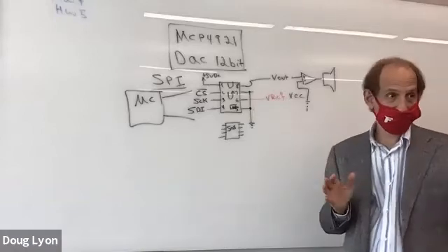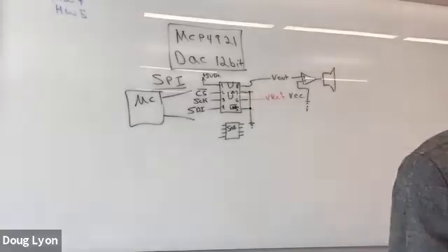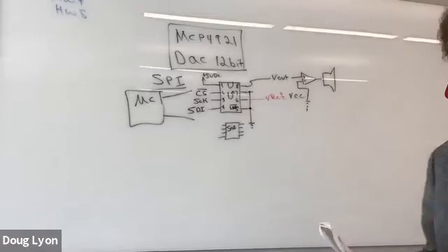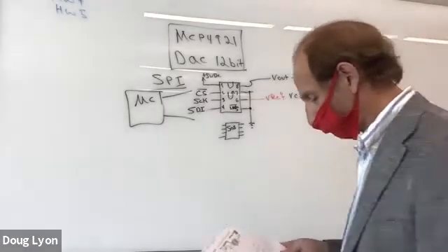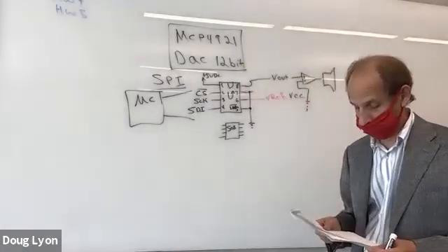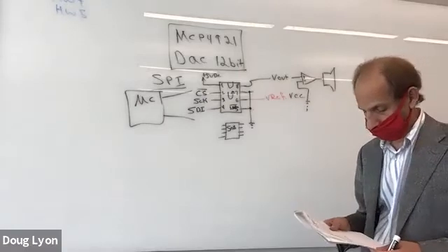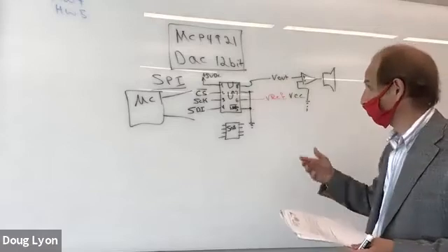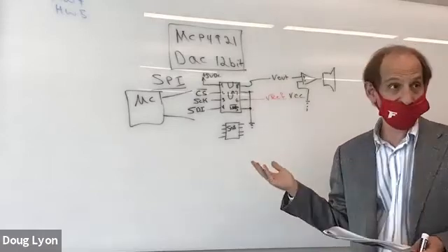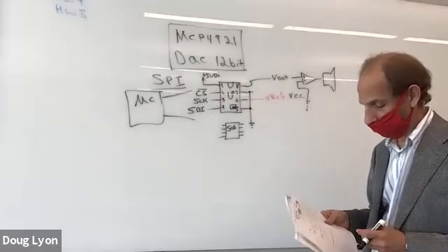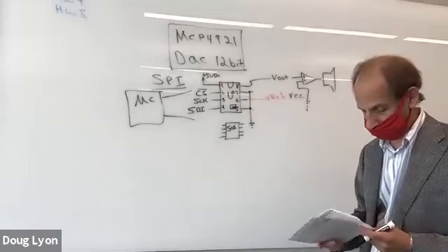What you want to do is use your PC speakers, assuming they're amplified, and then you're okay. Or you could use very tiny earphones, maybe for an iPod or iPad. But you don't want to try and drive real speakers with this thing. It's not going to go well. So iPod headphones will work. It's a standard stereo connector, a 3.5 millimeter connector. You can plug things into it, but don't just plug random things into it.